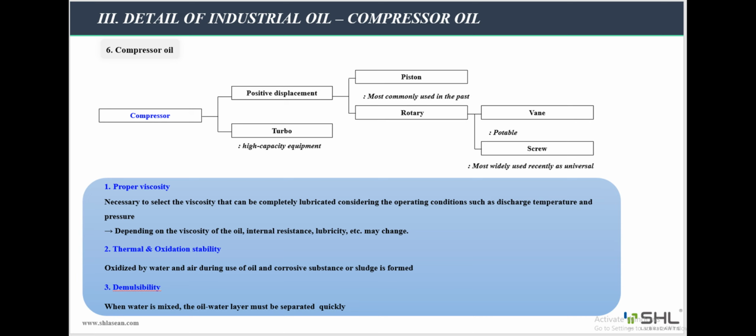Focusing on screw compressor oil, the oil has a lubricating, sealing and cooling function. The lubricant is injected into the pressure chamber between the rotors. It then forms a hydrostatic and a hydrodynamic lubricating film. The oil, therefore, lubricates the meshing rotors and the plane and roller bearings which are part of the geared coupling. Furthermore, it seals the gaps between rotor and housing. The temperature of compressed air is adjusted by the quantity of oil injected.